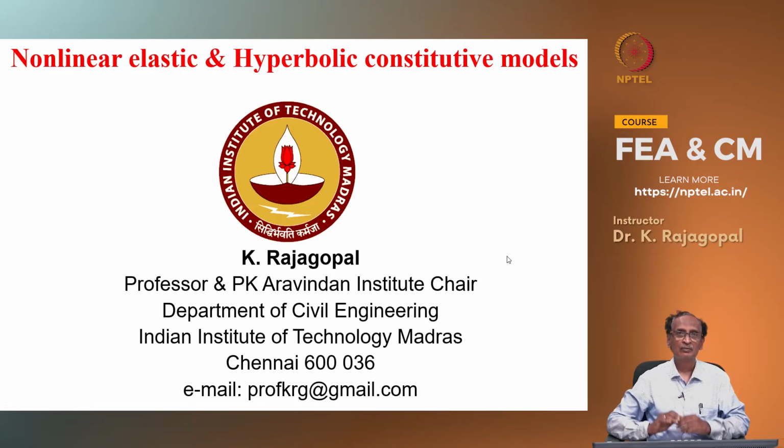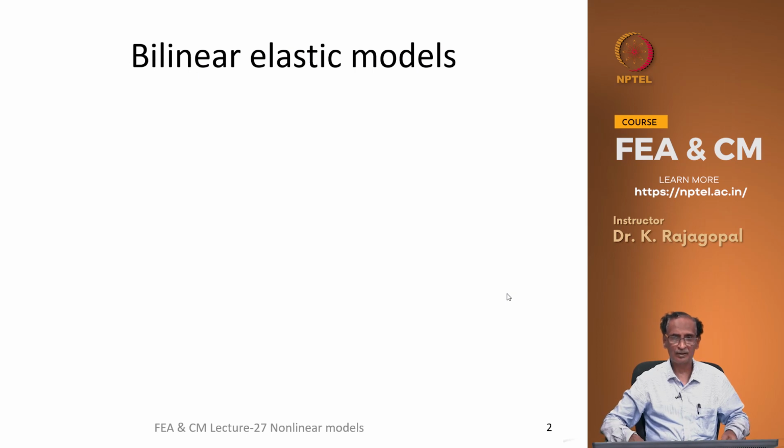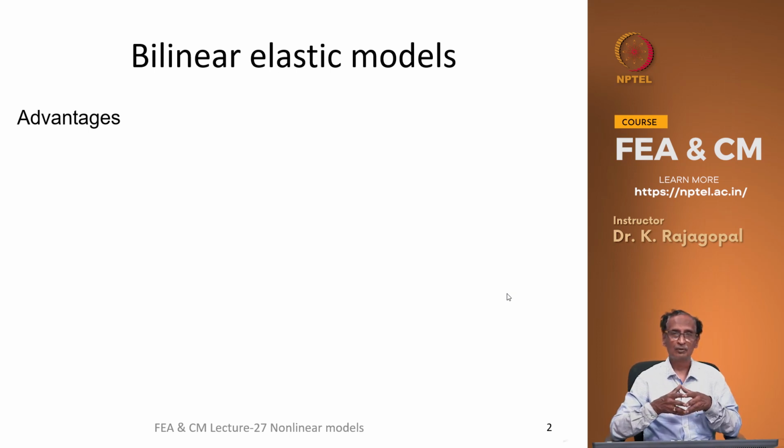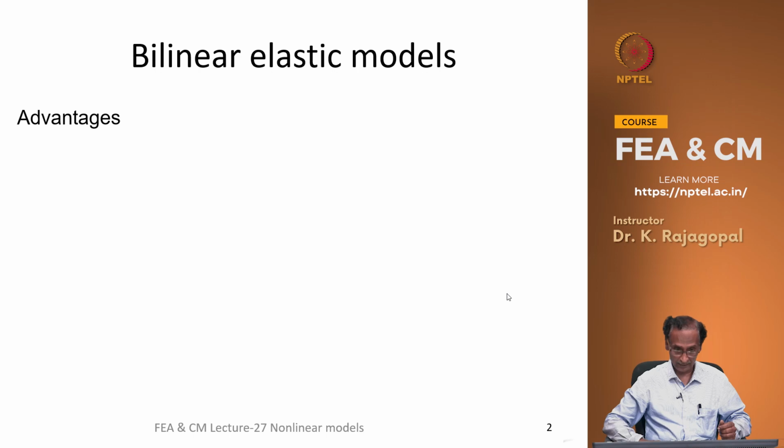Welcome back to our lectures on constitutive modeling. Till the previous class, we were looking at the linear elastic and then the bilinear elastic model. Bilinear elastic models we have seen in terms of the tangent shear modulus and the bulk modulus, or the tangent Young's modulus and the bulk modulus. And the advantage with those models is that we were able to put a limit on the loads that we can apply by introducing the Mohr Coulomb yield criteria on the shear stresses.